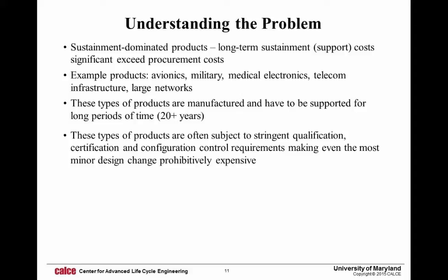The deal with these systems is that they're all subject to really stringent qualification and certification requirements. So it means that you can't just change things. If a newer part comes along, you can't simply use it as a replacement or a spare for an older part. In most of these systems, you can't do that. So there are prohibitive requalification costs, and some of these things are truly prohibitive. Changing out one part on one card in a large system may mean you're requalifying the whole system in sort of worst case.